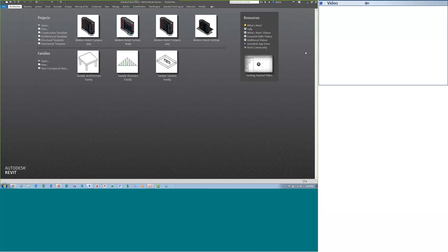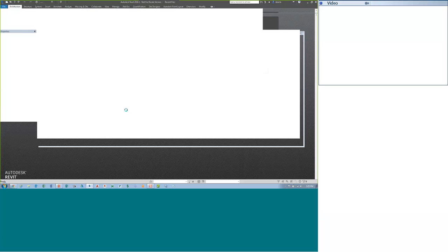Let's see, another question. Sometimes when I insert a specific object or component into my project, they attach to another component and move along with that piece of equipment when I move it. Is this an example of move with nearby objects? Yes. If so, how do I remove that setting? It's not really a setting that you remove by default. It shouldn't be checked. So if I start a new project